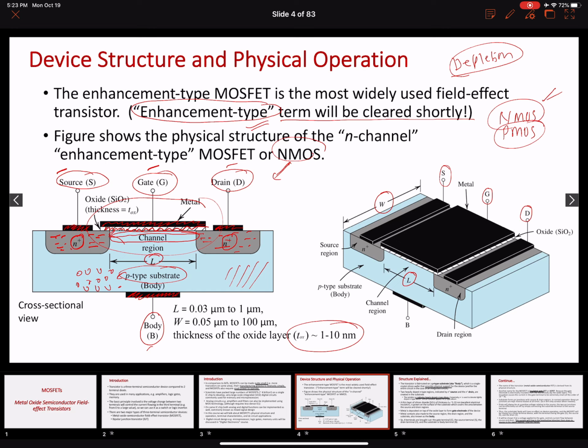We will discuss this in more detail again, but briefly speaking, in order to operate the transistors for different applications or for certain regions, which we will talk about in more detail, we just require the source, gate, and drain terminals. What usually happens is the body terminal is normally connected to the source terminal, or is grounded, or is connected to the negative supply in the case of an NMOS, to create a reverse bias condition, or normally off condition, for the transistor. What I just said about the body terminal will become much clearer again shortly.